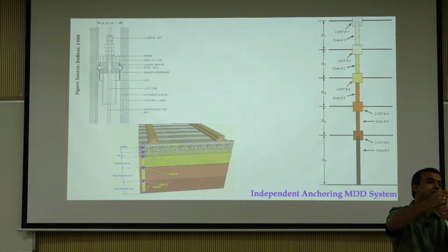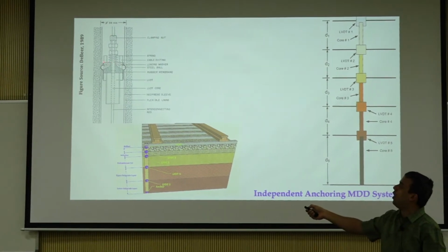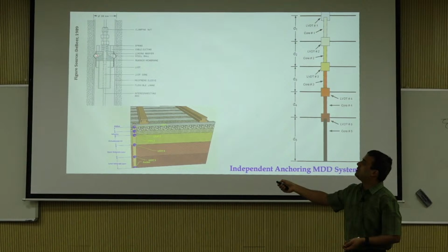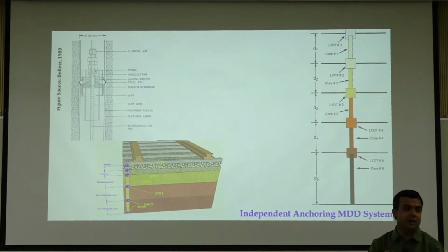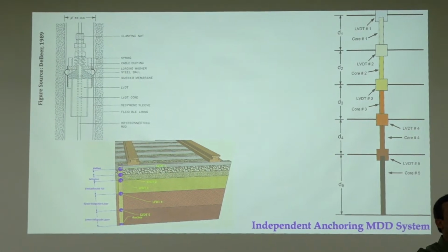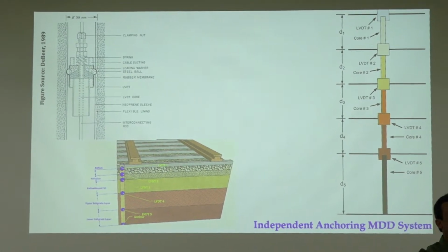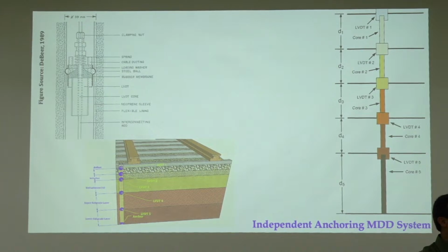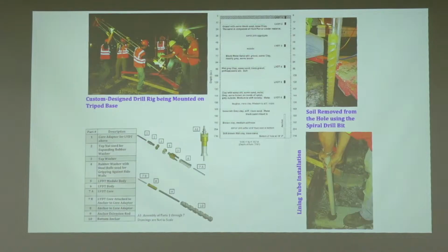When you rotate the screw, there is actually a rubber washer with some little balls that are built into it, and when the screw tightens, the rubber washer compresses, and in return it expands in the radial direction. When it expands, it grabs on to the side of the hole, and that's what mounting of the sensor is. Okay, so it's a very, very complex design, and we had to make all the sensors from scratch, and then we did this. This was the instrumentation stuff.